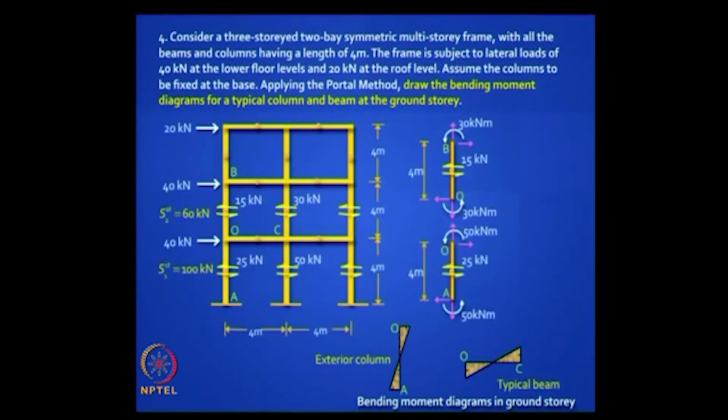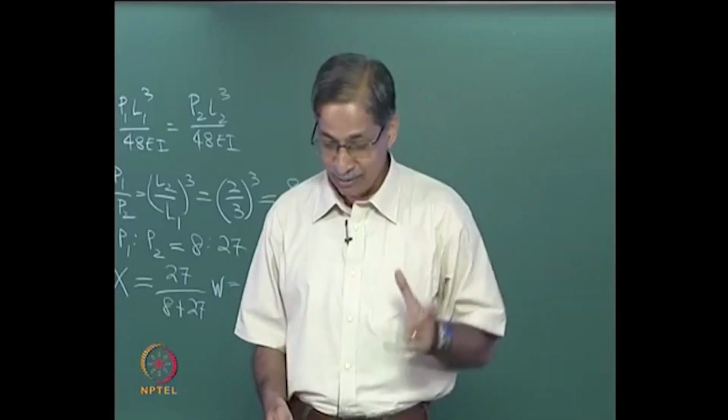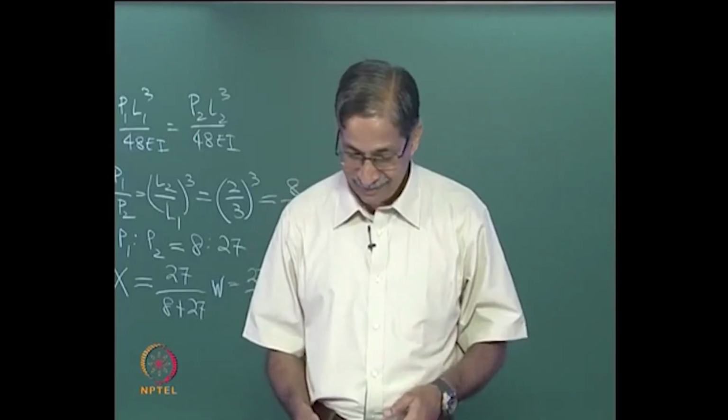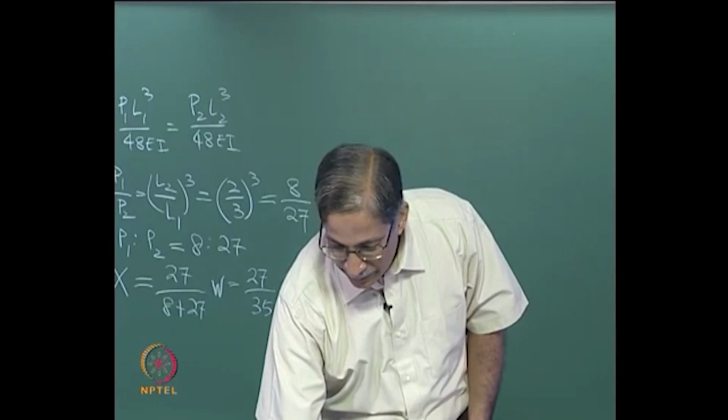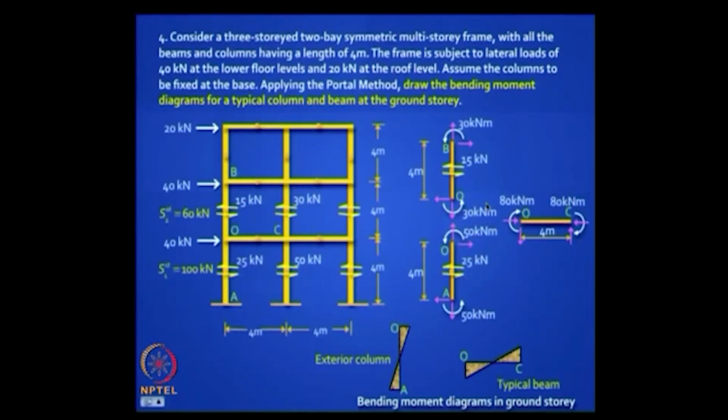And in the beam you have to also look at the story column. Some of you forgot that you need to add. It's not the entire 50 that goes here, you get something more from this 30. So 50 plus 30 adds up to 80. Some of you wrote 50, okay, so that's a mistake. That's it. These are your answers. If you do this, you get full marks.